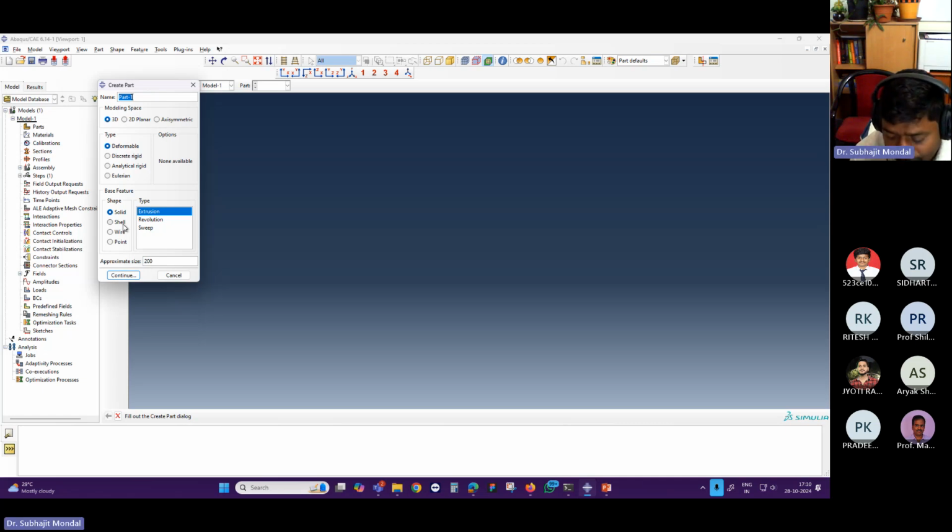Now, in the shell element, basically this is a 2D type of model. In the shell, we ignore the thickness. We are ignoring the thickness in the modeling stage, not in a real problem. We consider 2D modeling, and then we assume that there is some thickness, and we calculate all the things in the background, and then we analyze it. So one way is modeling as 2D. Another one is the 3D. In the 3D element, you have to model as it is, as it looks like.